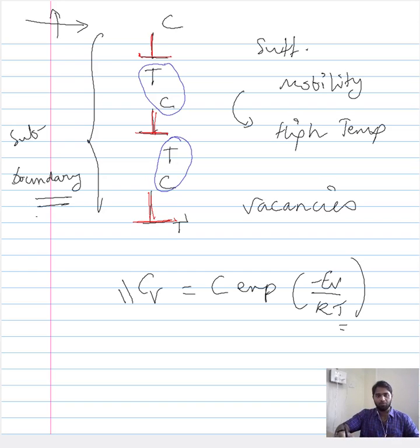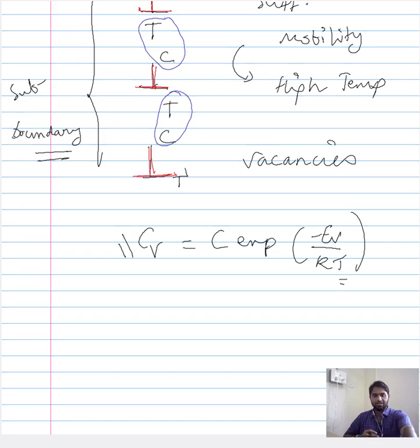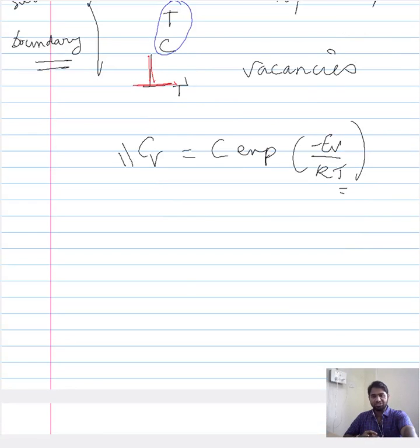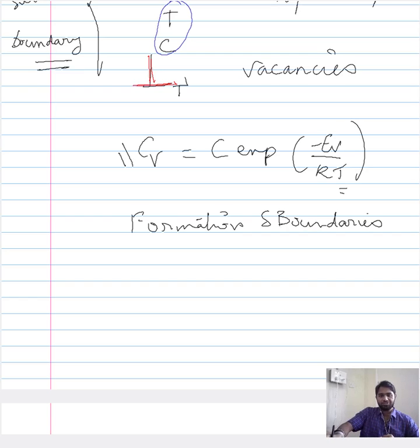Now, sub boundaries essentially reduce the number of dislocations. So once you have a sufficient amount of sub boundaries, the number of dislocations in the actual grains decreases. So instead of the dislocation being dispersed all over the grains in the polycrystalline system, you have now compiled them, arranged them into definite sub-boundaries. So the dislocations have now accumulated and formed the sub-boundaries.